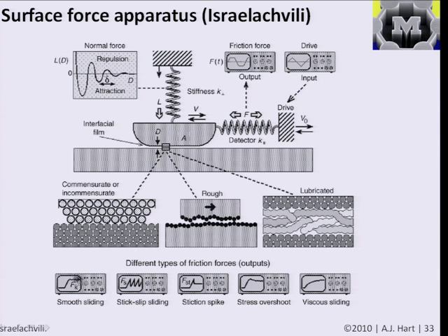And it just shows, as a schematic example, how different types of force behavior, as this upper piece is moved at a velocity over the lower piece, and as the force is measured with this spring, can be related to the characteristics of the surfaces. So the ability of these instruments to measure the practical aspects of real surfaces is also complementary to the theory that gives us the value of that Hamaker constant, when we're assuming an ideal geometry for a material, planar or spherical.